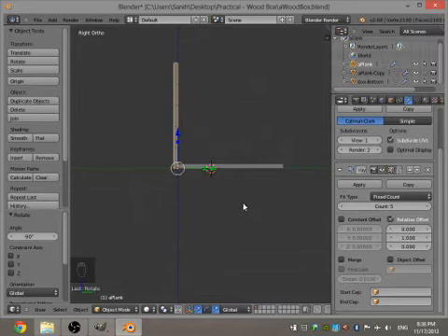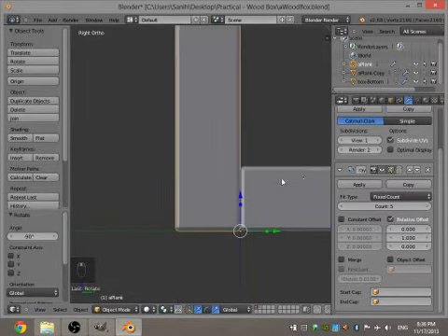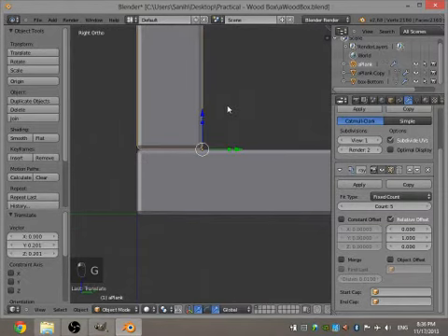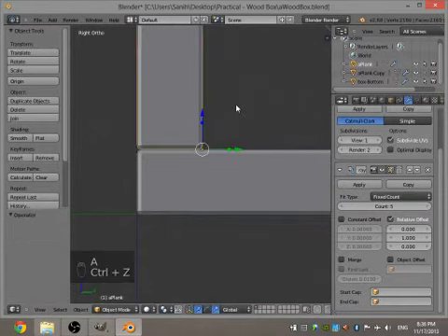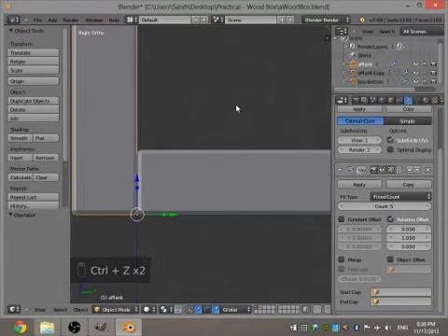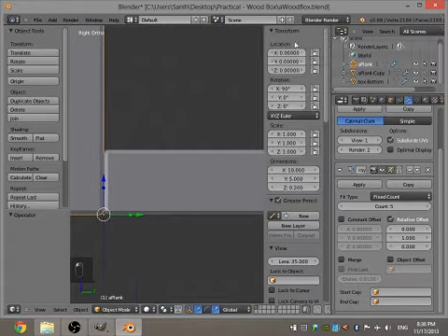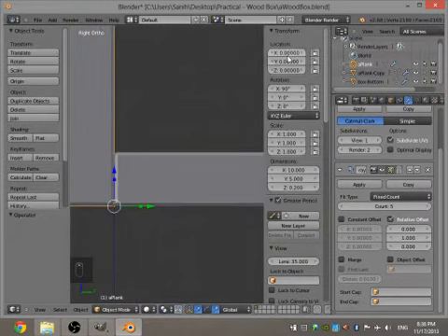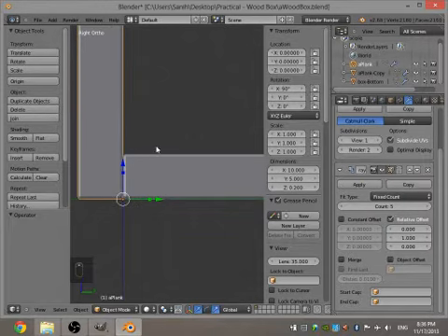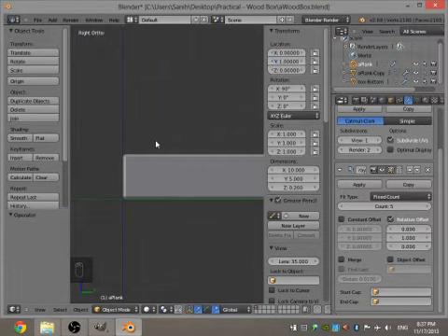Now here's the thing. 2 ways you can do this. One way that I would do it is just zoom in, grab, and then just move it up here. There you go, done. Correct? But if you really want to be anal about it, you really want to be accurate, points, right? So if I open this up, you notice that it's at 0, 0, 0, right? I need it to move along the y-axis 1 point, correct? So that means where? Y1. Right.